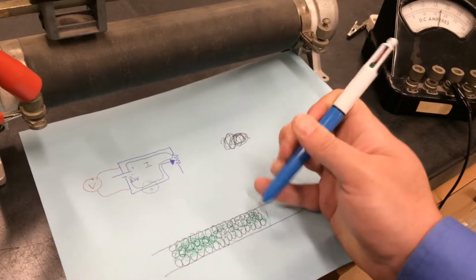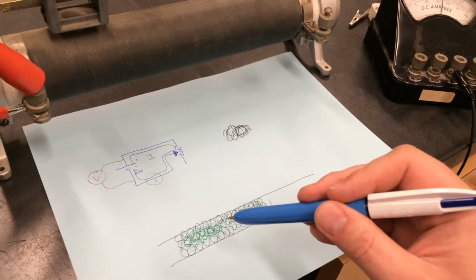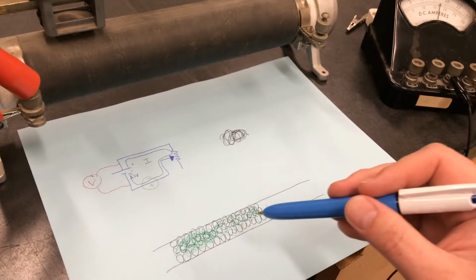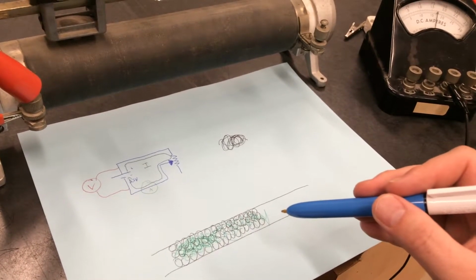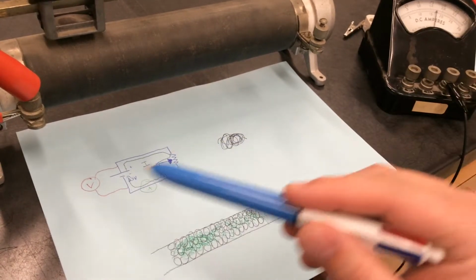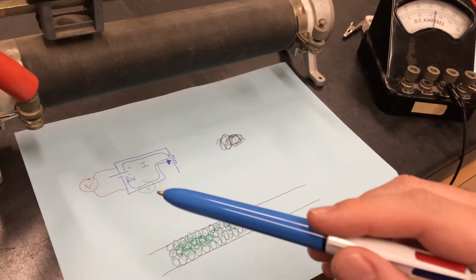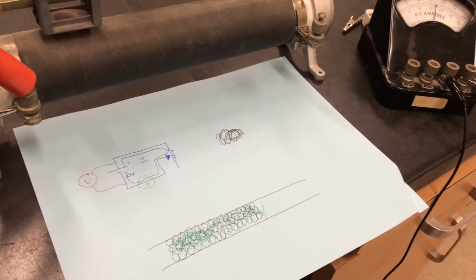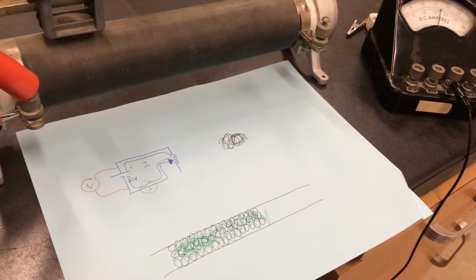And every time one of these atoms gets hit, it starts moving. And of course, motion of atoms turns into heat. So the longer you have to go through these atoms, the more energy you lose. And that's why we're actually seeing the current drop. The same voltage, the same energy per charge is not all going into making charges flow. It's partly going into moving the atoms. And the more atoms it's got to move, the less energy there is for the charges to flow.